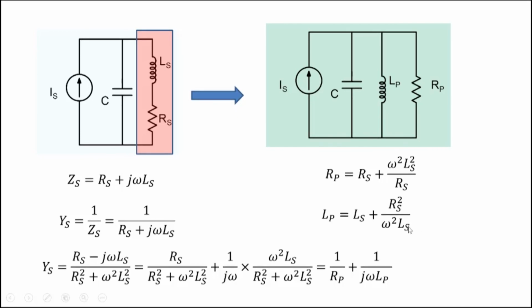Right, so now the zero power factor frequency, or zero phase difference frequency, or unity power factor frequency, would be the place where the reactance due to the capacitance cancels the reactance due to the inductance that is there. Okay, so that would be easy to calculate here once you do this kind of a transformation.